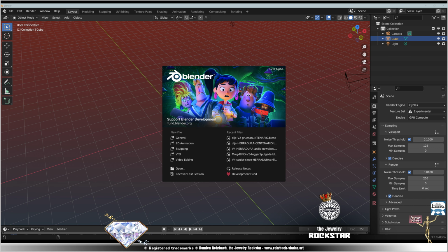So I'm going to use a size of 6 by 8 by 4. Okay, that's my oval shape, but we need to go to edit mode, Tab, switch to side view, Alt Z, Alt A, B, select these guys, delete vertices, and now we're going to smooth out the bottom part. Let's go to the move tool, but let's do an extrude first on the Z-axis here. Once, make it a bit smaller.